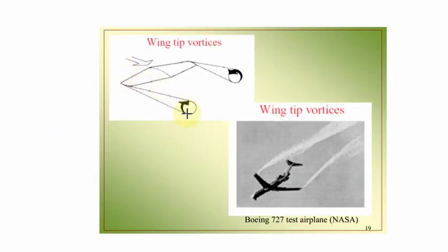See here, this is the formation of the wing tip vortices. In a real aircraft we face it like this. Suppose the first aircraft is a heavy aircraft and the second aircraft is a light aircraft; the impact of the wing tip vortices is still available in the airport or in the atmosphere. That is why we do not operate aircraft continuously. There are many examples and accidents available on the net, you can search for them. When a light aircraft follows immediately after a heavy aircraft, the light aircraft may lose its control. That is why our ultimate aim is to reduce the wing tip vortices.